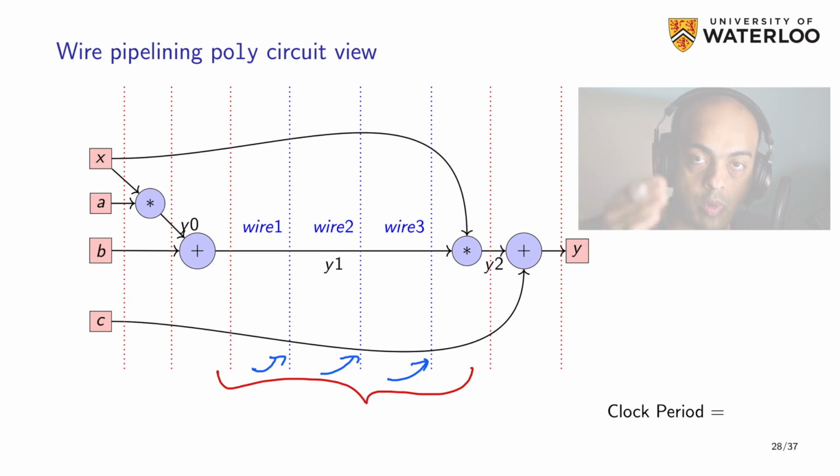Right? If you do nothing to the wire, it's going to grow very aggressively, so the speed drops off dramatically the farther away things are. There are things you can do to the wire to make it high performance that we'll cover later. But even with that, one thing we need is to be able to partition those long wires into lots of smaller wire segments and then place a register along each of those segments.